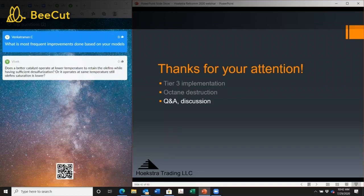I should have made clear, I guess, I'm talking about conventional fixed bed desulfurization, selective desulfurization here. The extraction is an alternative route that I think works. It allows you to save octane like you can with this process. It's less commercially developed in terms of number of references, but it's something I have no reason to not consider as an alternative if someone's going to invest money.